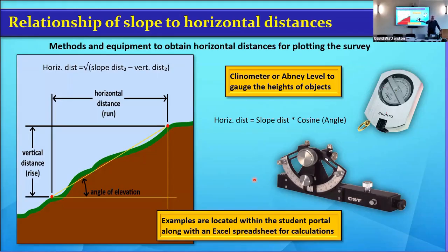So you would walk up the hill, you'd have a pole at the same height as you're observing, up the top of the hill. You sight the top of that pole, and that's the inclination. And then you can work out by trigonometry the horizontal distance, and that can be your measurement that you're going to draw on your plan from point A to point B.